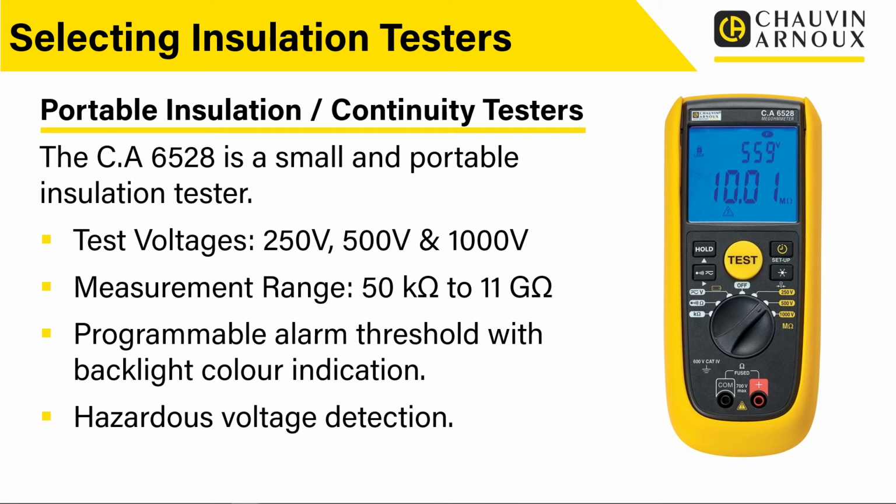Now this will carry out testing particularly suitable for the normal low voltage type insulation. So it'll do test voltages of 250 volts, 500 volts and 1000 volts DC. It's got a really wide measurement range, which goes from 50 kilo ohms all the way up to 11 giga ohms. So we're talking way up, above mega ohms, we're into giga ohms. And that means we've got a good range of values on this.